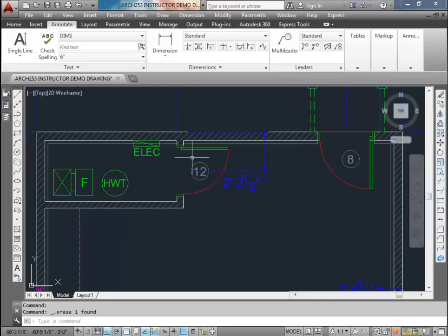It should be fairly obvious, though, that we are centering that door in the wall. So even if we didn't want to include that dimension, we wouldn't have to because there would really be no location that they'd be able to put it. If it was really important that it got located a certain distance from the outside wall, then you would definitely want to put a dimension on it. But having said that, I don't really think we need it there.